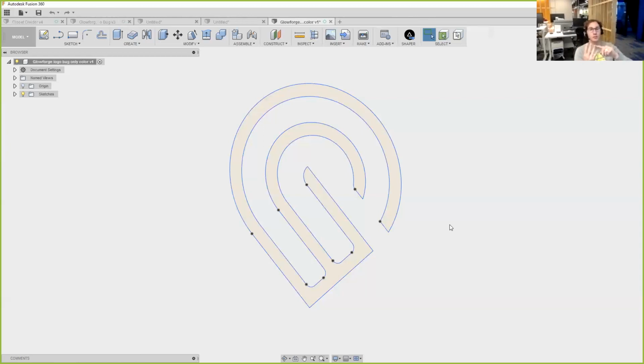Option number 2 was the insert of DXF. It also came in with pretty good geometry, but it didn't give me the full ability to rotate or scale. So between the two, I would say right off the bat that I would rather insert an SVG than insert a DXF. Then in terms of uploading, the SVG was pretty useless, so I don't recommend that one at all.